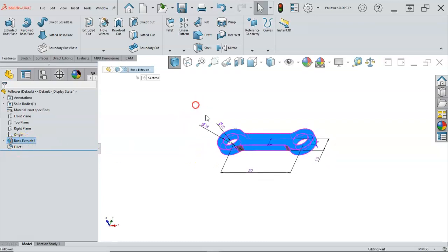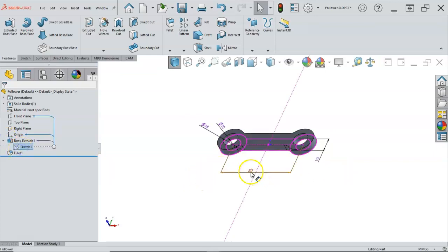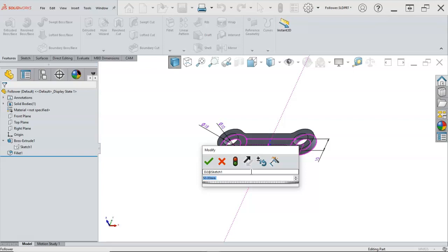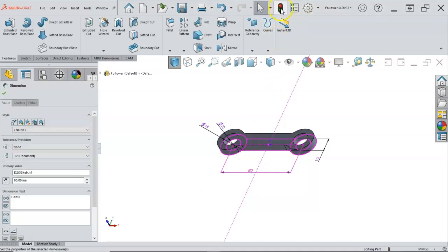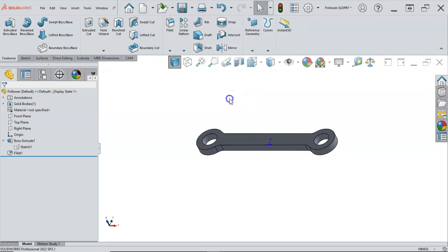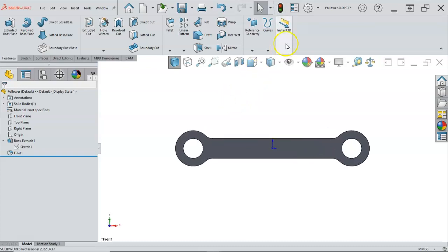The extrude will give you the thickness as well, where the sketch will give you all of the sketch dimensions. So I'm not even going into the sketch, I'm just making that adjustment, 80 and enter. And if I don't hit the rebuild in the modify, then I have to hit it up on the title bar, or the standard bar.